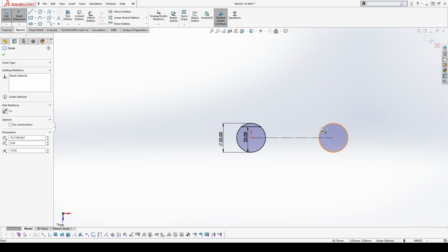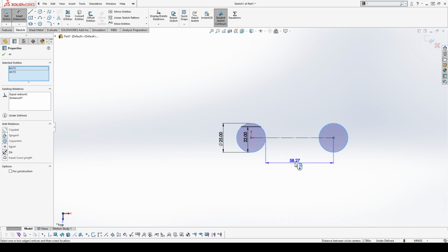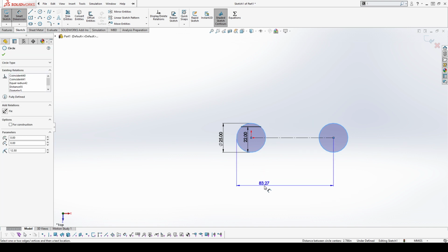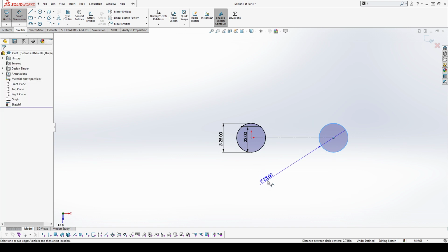So let's say that I just normal clicked on that one, starting to measure from that center point. Shift click over here. See, it's measuring from the center point of one circle to the closest edge, or the outside edge works as well. So I can combine both those different types if I wanted to. So that's how we can mess around with arc dimensions.